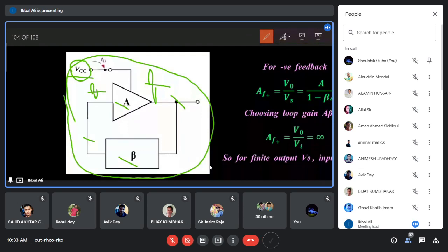And that noise is a very small, fluctuating current or voltage. And that noise contains all the frequencies from 0 to infinity. All the frequency components are present in that noise. So in every part of this circuit, you have an electrical noise, which is a very small amount, maybe lower than a millivolt or milliampere, maybe a microvolt order of noise is there. Very small voltage fluctuation or current fluctuation is everywhere in this circuit.